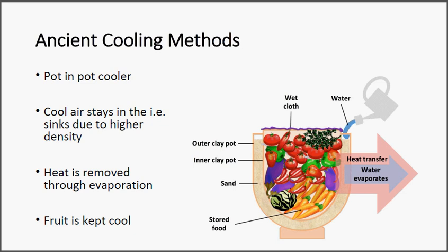So then you put the area, the stuff that's been filled up with sand between the 2 pots, you fill it up with water. So the sand is going to be soaked in water. And then you've got the outer clay pot, the inner clay pot, and you put a wet cloth over the food. And then, as the water evaporates, it will naturally, through evaporative cooling, cool down the inside of the inner pot.